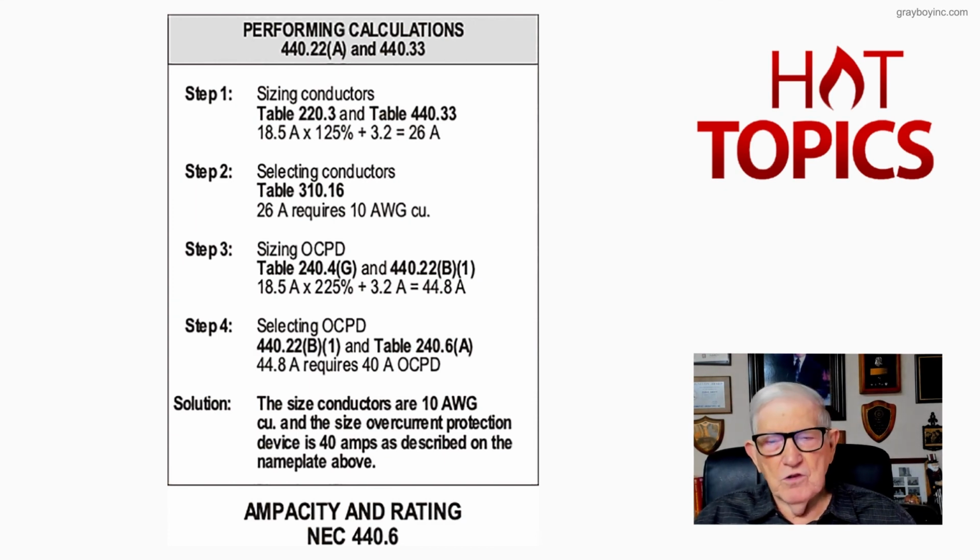But this is just a good illustration here in 19-1B, showing when you do not have a branch circuit selection current on your nameplate, and you only have the values like 18.5 compressor, 3.2 condenser motor, then this is the calculation you would run. Most of the time now, you're going to have the branch circuit selection current, and as an electrician, that's all I have to go by, because all the math is already done for me, see.